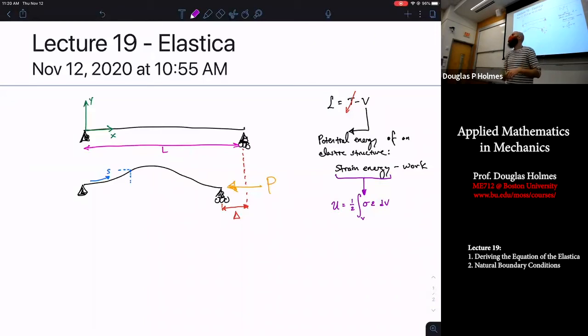How do we know that? Well, you've all probably taken a piece of plastic wrap, or maybe a piece of aluminum foil is a better example. You could cut a strip of aluminum foil and do this and come back, and it'll stay flat if you're careful. And we all know that aluminum foil is so easy to plastically deform. You just twist it a little bit and you get creases everywhere. Those are plastic deformations that you're not going to get recovering back to their initial state. But if you're careful, you cut a little strip out of it, you compress it a little bit, it'll go back and forth, and it won't leave any permanent deformation.